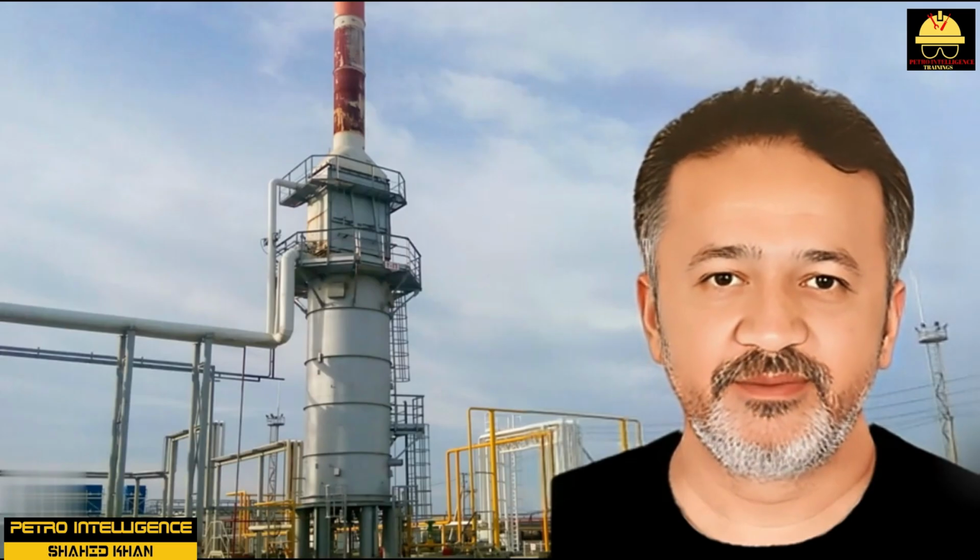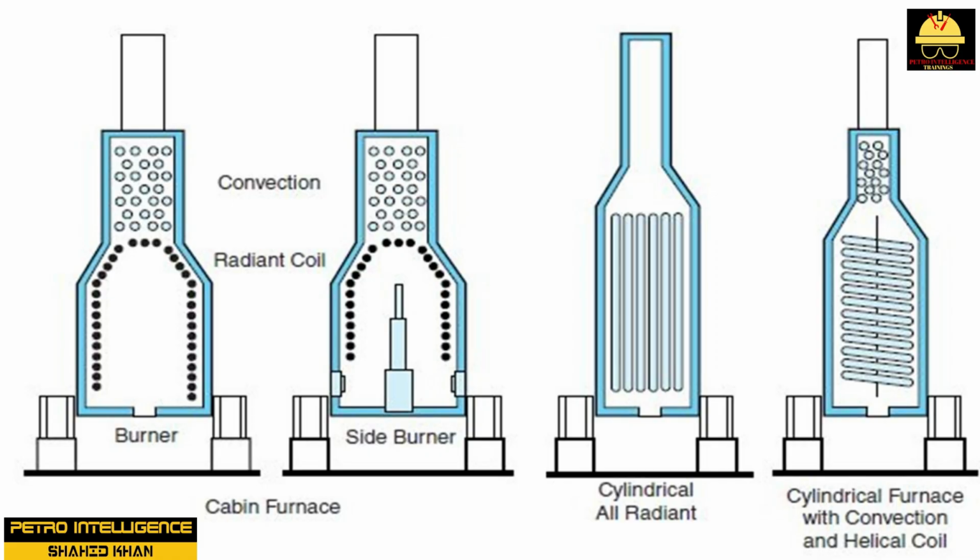Cylindrical furnace. Another very popular direct-fired heater design used by industry is the cylindrical furnace. The simple cylindrical furnace is engineered to utilize the radiant heat that emits from the burner at the bottom center of the furnace. Heat transfer is primarily radiant unless special options have been added. The cylindrical nature of the furnace enhances draft from the lower radiant section, through the optional convection section, and out the stack. The vertical tubes are typically composed of alloy steel.